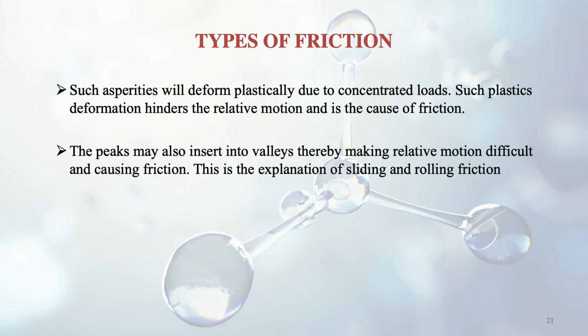The peaks may also insert into valleys. There may be some valleys also, like crests are there, troughs are there in a curve. So there may be valleys, and the peak may go inside, and it will make the relative motion more difficult and increase the friction more. So this is one kind of explanation of sliding and rolling friction.